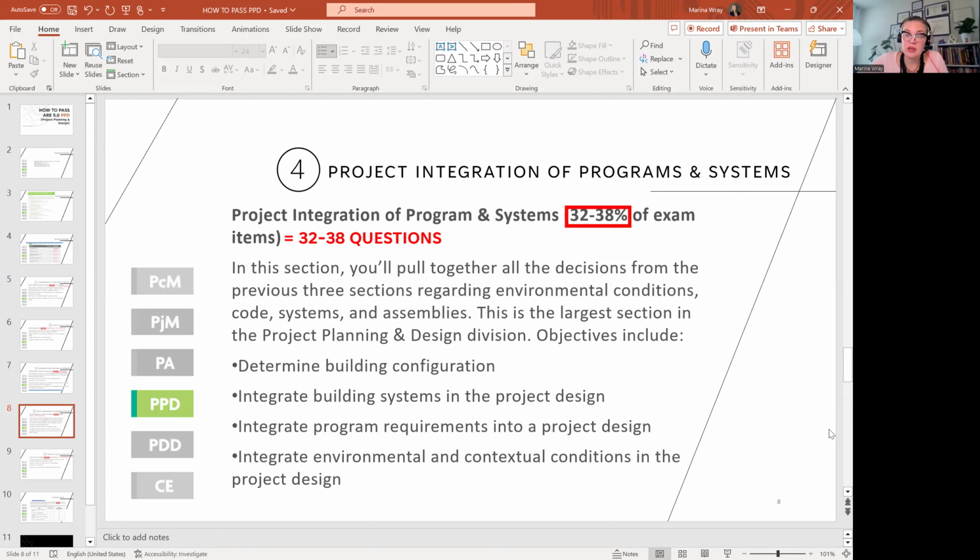If you want to do the LEED certification for the building, because later it will be very difficult to do. And here you check the specs, you incorporate that, and you make sure that everything is included. So for example, if you want to include the LEED requirements, you go to Division 1, I think it's like 018113.